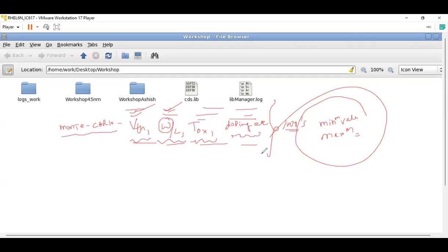See what these simulations will give you. These will give you a lot of statistical insights. Like this will give you parameter sensitivity. How sensitive is your parameter? Suppose you have claimed that my device is going to have 32 picosecond delay, and your Monte Carlo simulation is saying the minimum is 28 picosecond and the maximum is 42 picosecond. Then you cannot claim 32 picosecond.